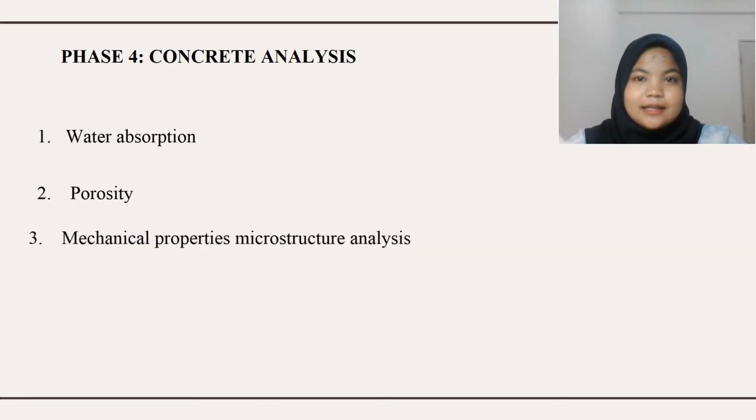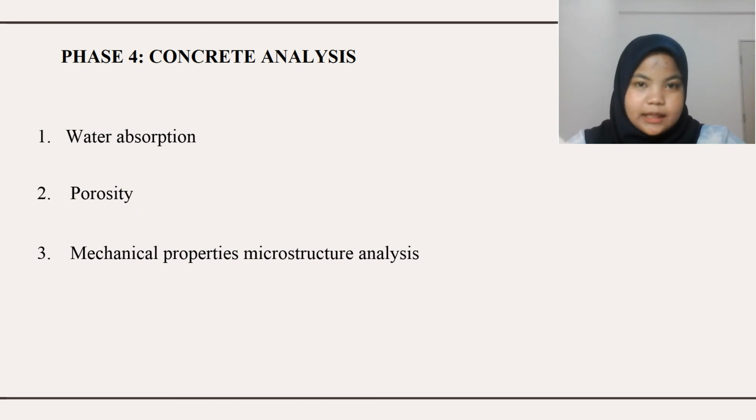The last analysis is mechanical properties and microstructure analysis. It focuses on mechanical properties, which is compressive strength. The microstructure of the concrete mix will be investigated using SEM, which allows the microstructure of the hydrated cement paste to be visualized. SEM analysis will be done before and after compressive strength testing to know the difference between before and after.